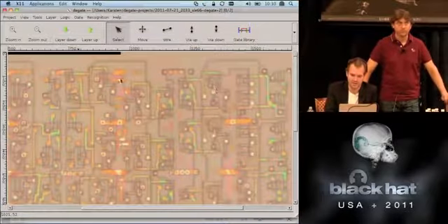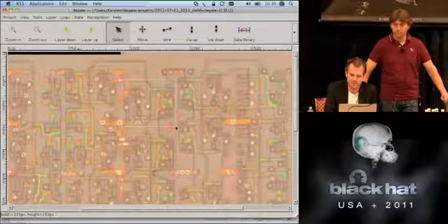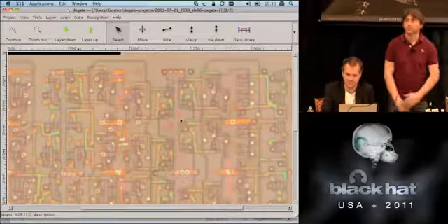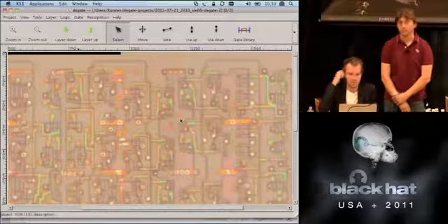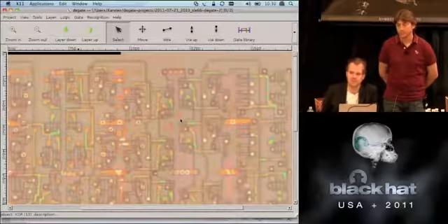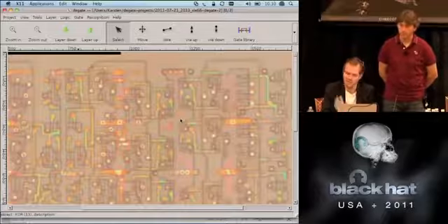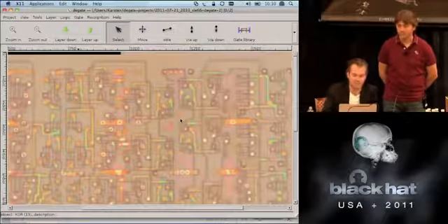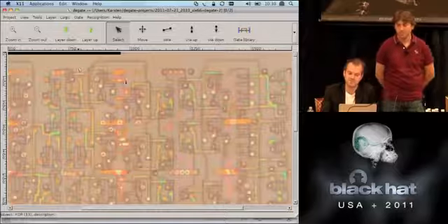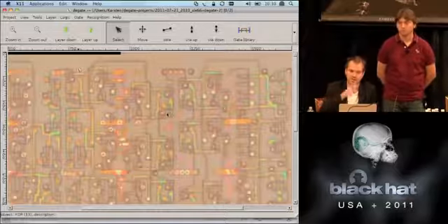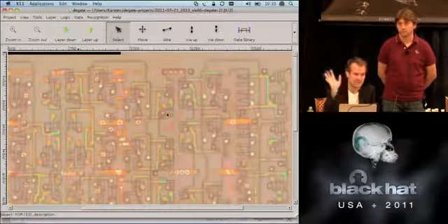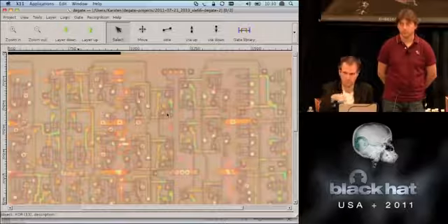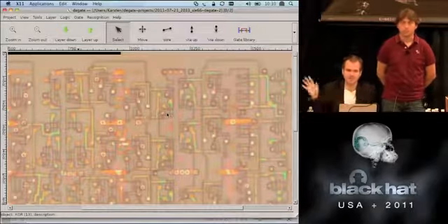And if you tell the software, hey, here's one gate, it will find all the other gate instantiations on the entire chip. For this memory encryption, there's just maybe 25. Sometimes in other libraries up to 40, but never really more than 50. I don't think we've seen a library with more than 50. So you do this 50 times, finding places on the chip where no gate is marked yet, and you mark it, and it finds all the other places, and you get quick coverage.